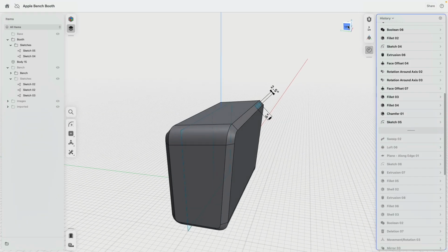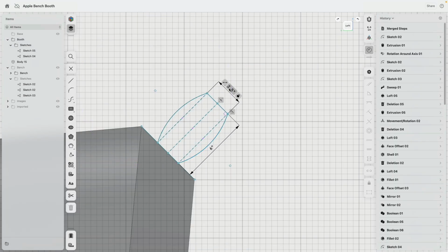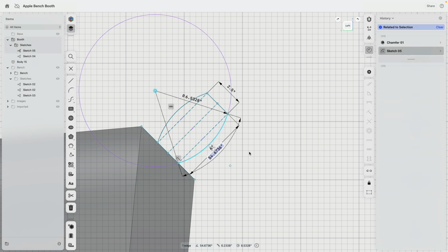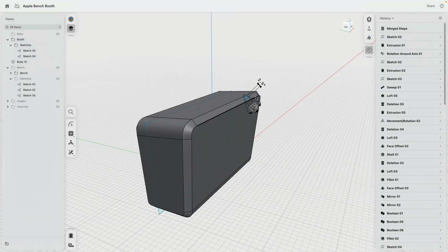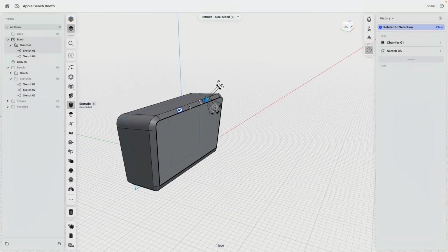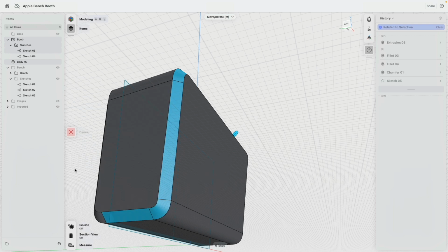I went to this side view and created the sketch. Here you can see the dimensions, 2.5 and 6 inches. Yeah, that looks like 55 for the arc. This is also centered. These lines are perpendicular to this line. I drew this line first. This line is parallel to that line. So everything is at a nice 90-degree angle. And then when you're done, you can simply select the sketch profile and click, click, click, and click, click, and do a sweep.